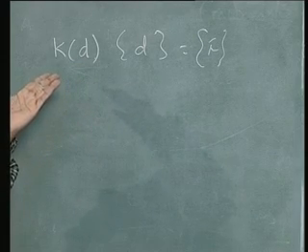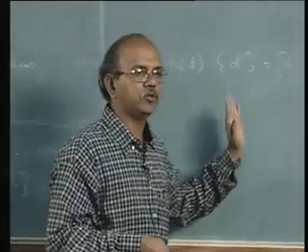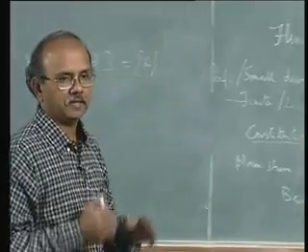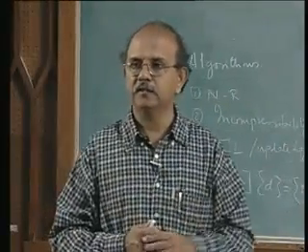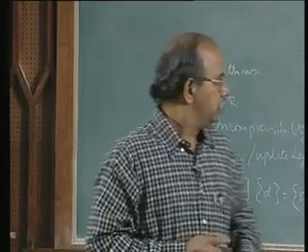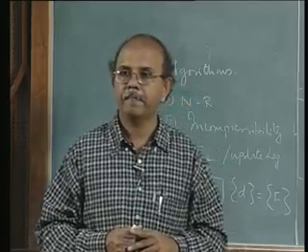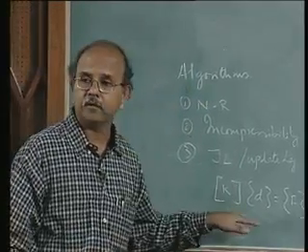Is that clear? Anyway, we are going to see quickly, the whole idea is to quickly get in and see how we are going to solve these problems and get to know the whole issues of nonlinear analysis by using a one-dimensional case. So the first and foremost lesson: in nonlinear analysis, we have k dependent on d, while in linear analysis, we have k independent of d.